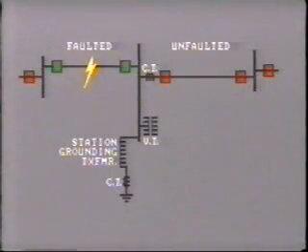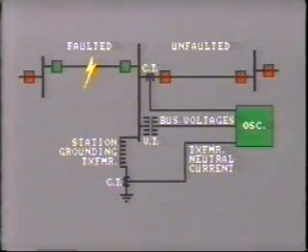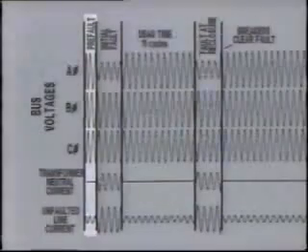In practice, this happens quite frequently when the line does not stay de-energized long enough for a temporary fault to clear on its own. In this example, the oscillograph has captured the substation bus voltages in all three phases, the transformer neutral current, and line current for one of the transmission lines. The oscillograph system in use here can record 3 cycles of pre-fault data.